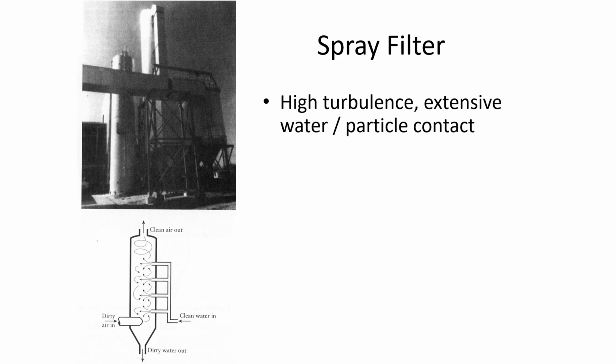Another way to clean out particulates is to spray water into the smoke. And if you've got dirty air coming in and it's going up a smokestack and you're spraying water in there, then the vapor or maybe the little droplets of water are able to cleanse the air as the air is going up. Just in the same way that, you know, on a dusty day after a rainstorm, the sky is more clear. This is trying to basically do that same thing using like an industrial engineered process.